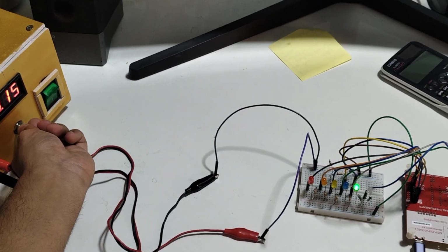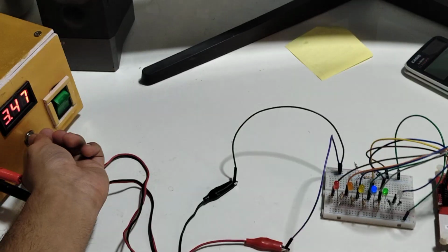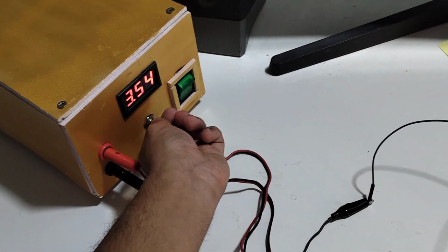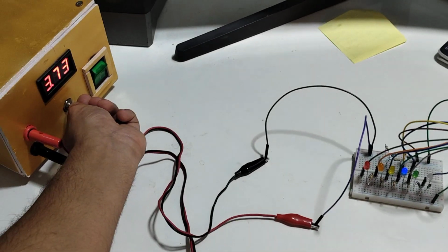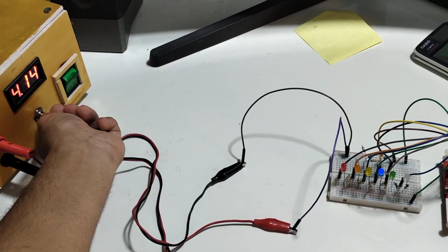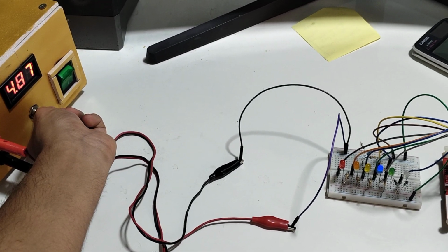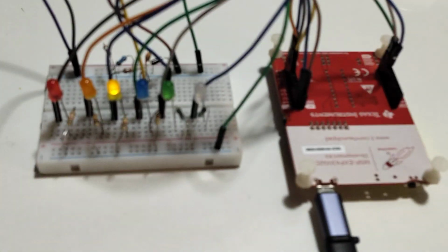3, and you can see now we're at roughly, there's a flicker because that's the transition point, so both are sort of glowing. And now you can see we're clearly above 3.3 volts. We're at 3.7, and now the blue one is glowing, the rest of them are off. So we know our ADC logic is working. Let's continue. The next threshold is going to be 5 volts. So now we're close to 5, and yeah, the flickering has begun, and now we're above 5 and the yellow one is lighting as expected.